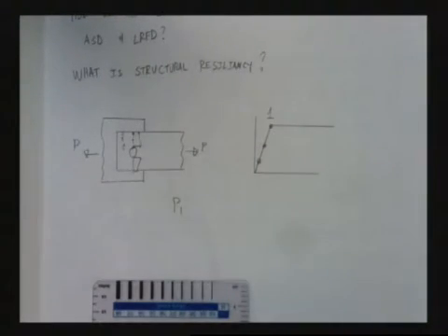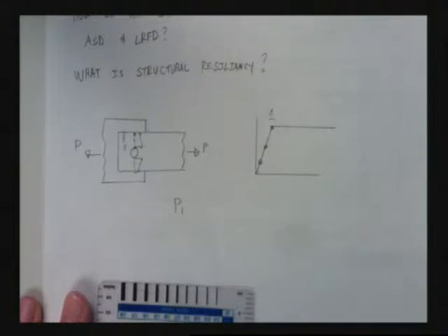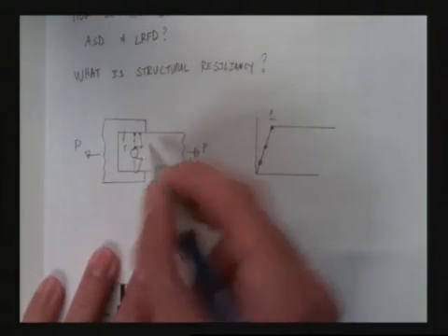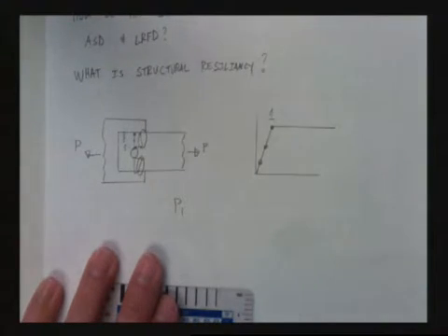Structural resiliency tells us it's either when one element is overloaded or when all of them are. When we talk about elements, in this case, we're talking about this area. When all of this area is at what point? Yield, but actually you'll find out in the code we use fracture. We don't use FY, we use FU. How much higher is FU than FY? 10 to 15%.